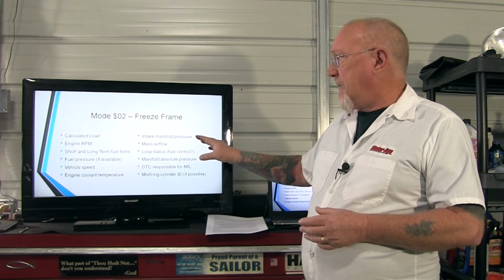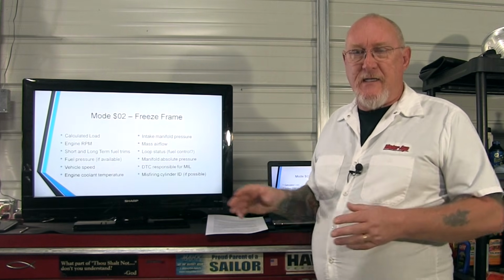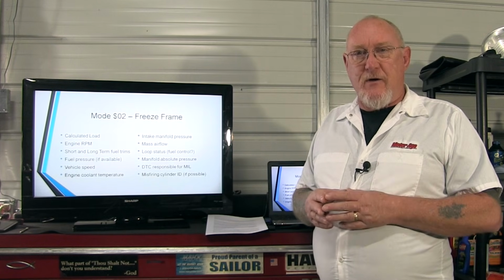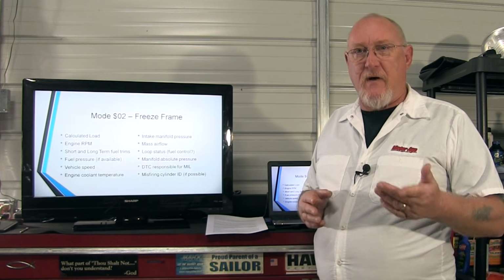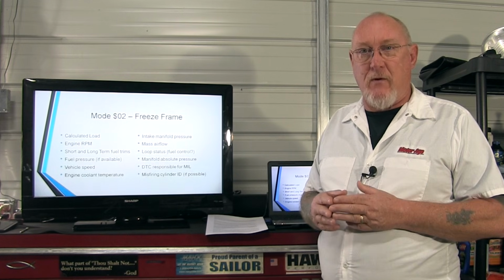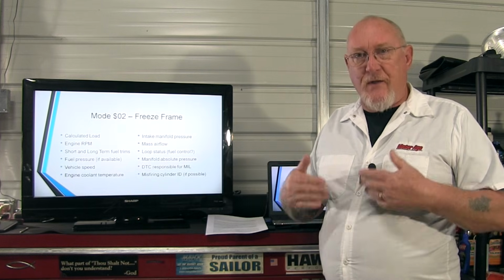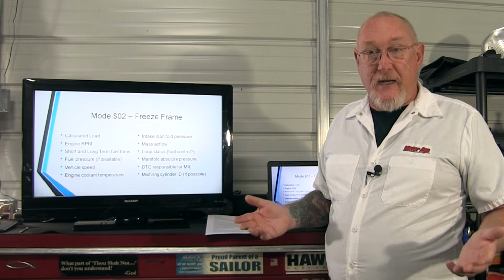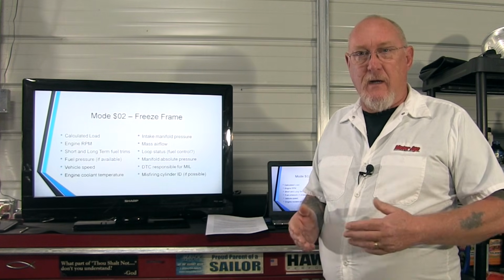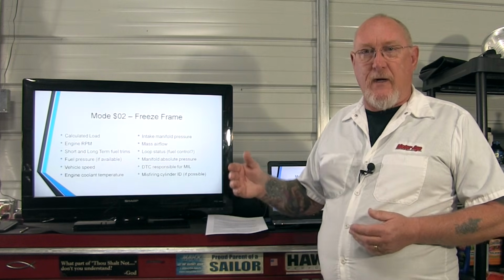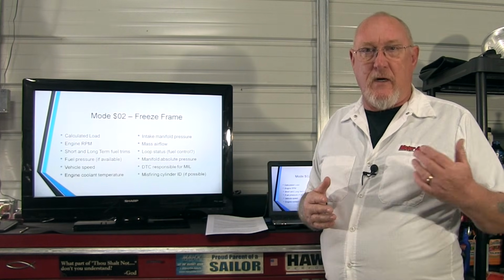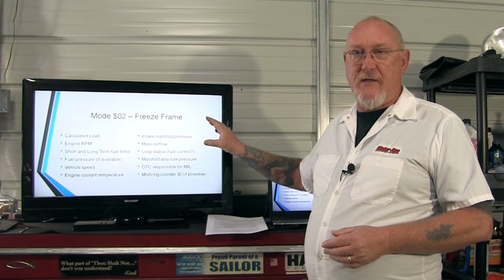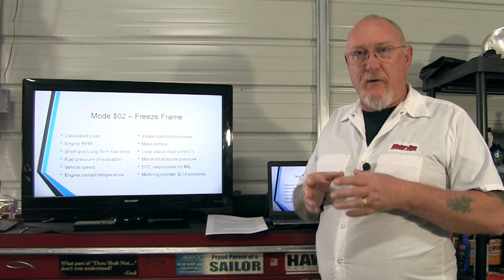The other thing I want to point out about freeze frame data is that it's most valuable for those continuous monitors. If you remember the continuous monitors that we talked about last time, the misfire, fuel system, and comprehensive component monitors, these are monitored all the time, or continuously, while the vehicle is up and running. Misfire is a great example. That misfire could be occurring at idle, or at highway speeds. It could be occurring when it's under load. It could be occurring when it's decelerating. This is the information that's going to help us make that determination so we can actually recreate and fix that problem.